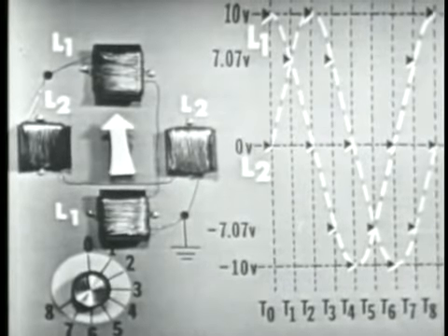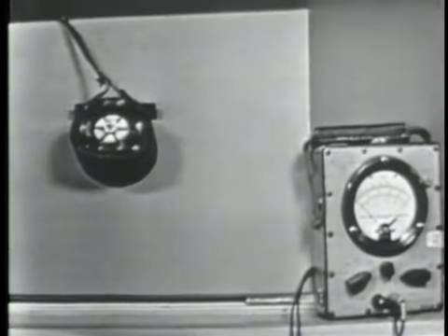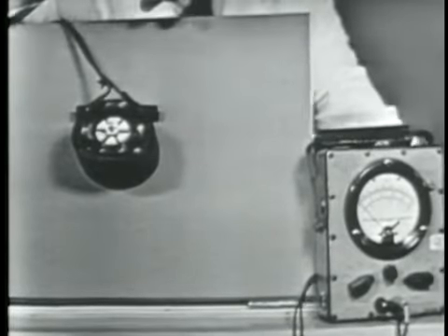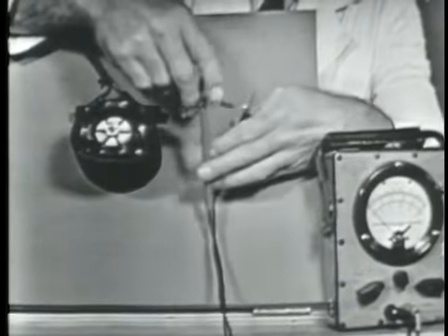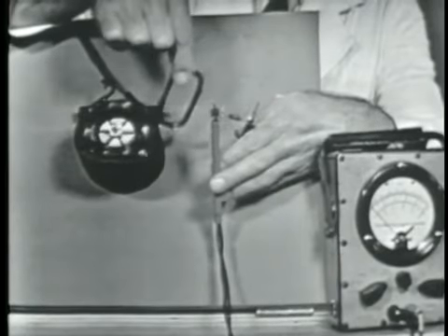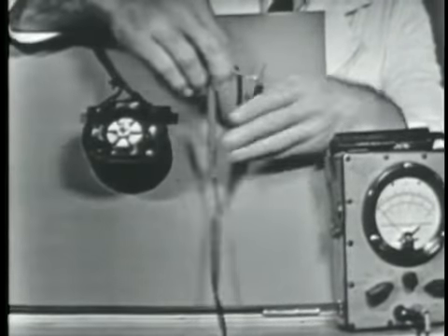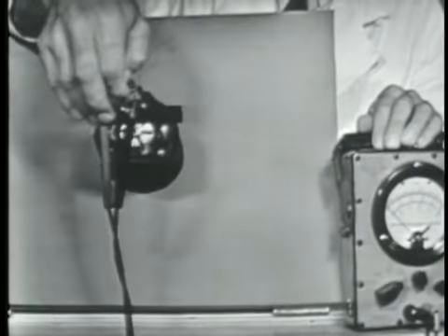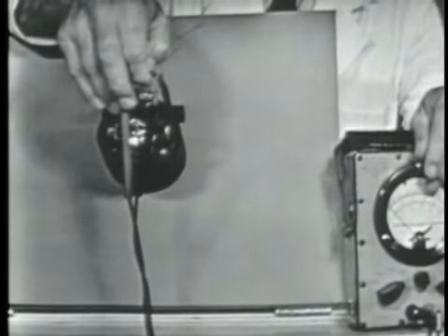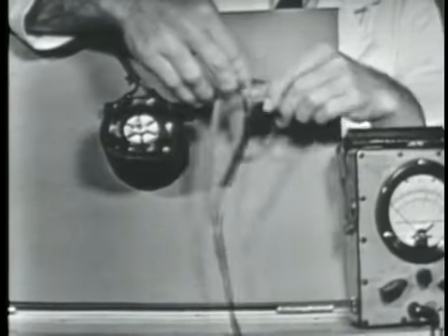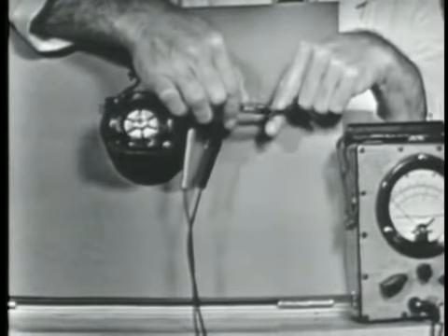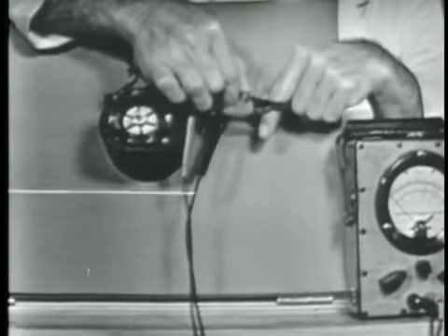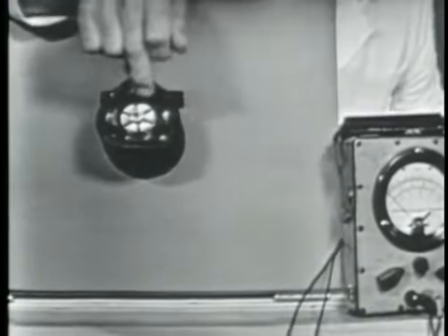Right. Now, I'll take item 4. All right. Help us out. All right, item 4, the rotor acts like a magnet. Well, it actually becomes an electromagnet and follows the rotating magnetic field because of induction. Okay, and we proved that with this little loop of wire, the resistor and the PSM6. We put the loop in the field windings, and the PSM6 showed us that we did have a voltage induced into the loop, causing current to flow. Once we had current flow, we know that the loop had to become magnetized and exhibit a north and a south pole. And once we get it magnetized, it has got to follow the rotating magnetic field.